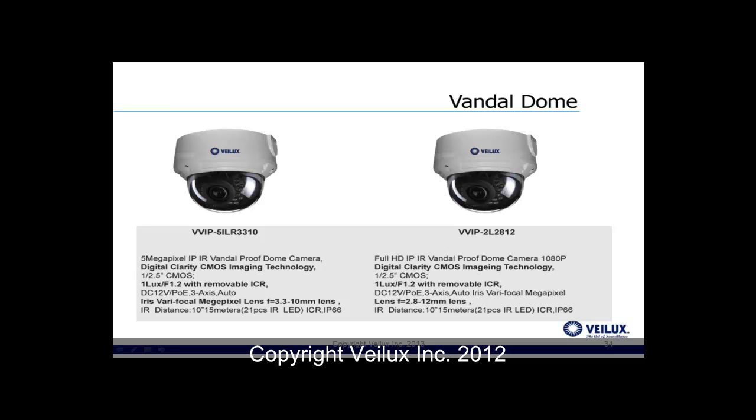The VVIP-2L2812D is a full HD IP IR vandal-proof camera with 1080p picture. Digital clarity CMOS imaging technology, 1 lux, 1.2 with removable IR cut filter, 12 volt DC or PoE, 3 axis, auto iris, varifocal, megapixel. Lens is a 2.8 to 12 millimeter lens. Distance is 10 to 15, 21 IR LEDs with IR cut filter, and the IP rating is 66.